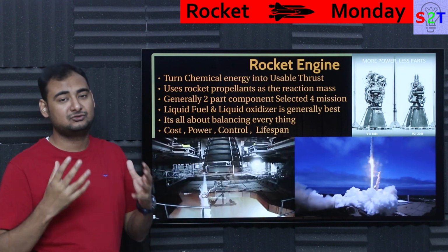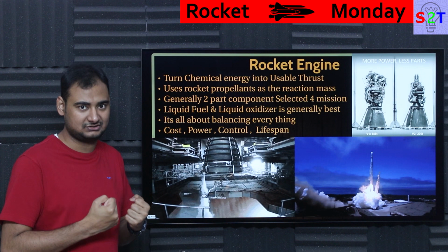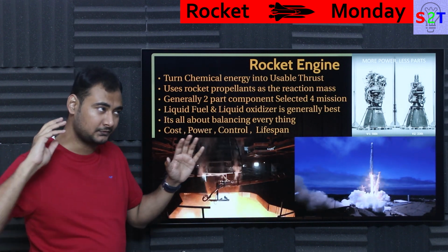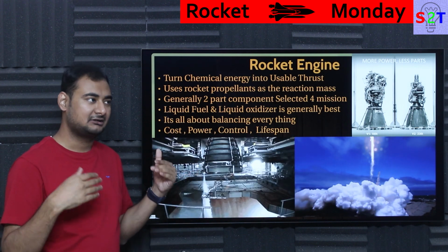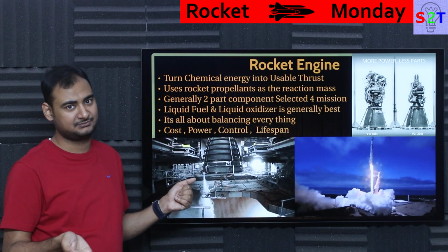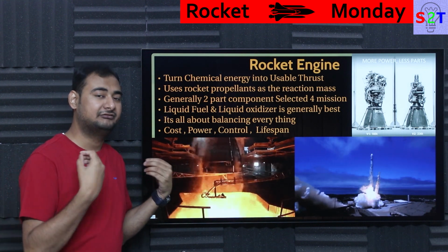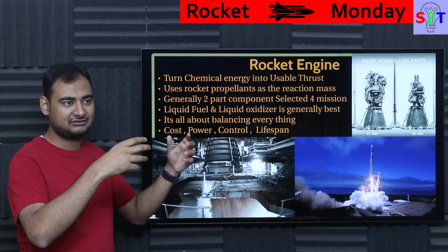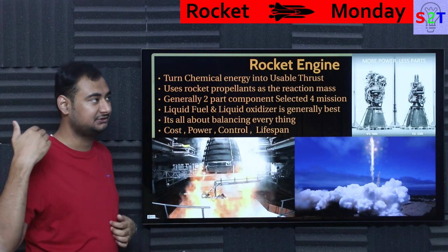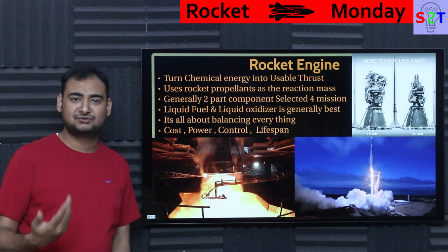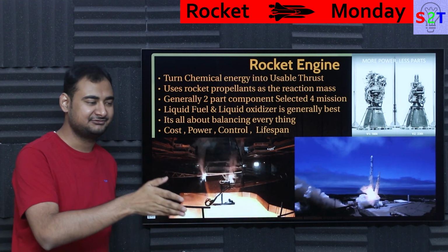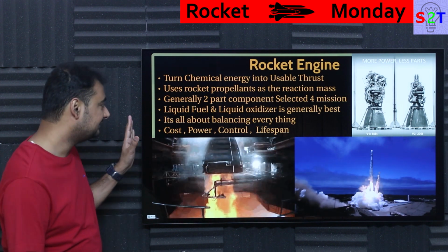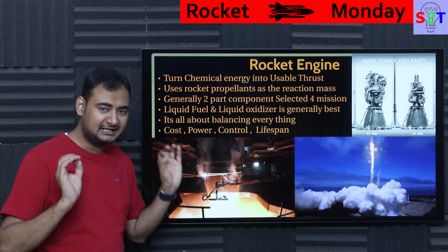So it's really good if you do not need too much velocity, but you need a lot of thrust, so to say, first stage. But if you are in upper stages and you really need to throw things far out, you will see people always choosing things that have hydrogen in their upper stage, because that allows you to get higher velocity. That does not have as much oomph, but does have velocity. So you use RP1 to get off the ground, and you use a hydrogen upper stage to send it very far away. Or you can use methane, which is a good enough compromise between RP1 and hydrogen, where it gets both parts done. And it's all about balance. Balance is the critical aspect of it.